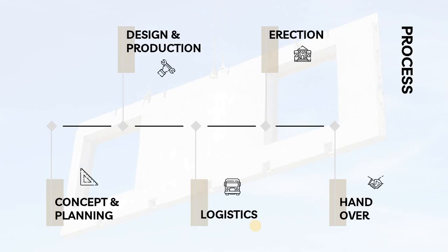The element will be placed in special transporting equipment, and then the loaded material will be transported to the site where the material will be offloaded by a special crane, and then the erection of the element will be done directly from the trailer.